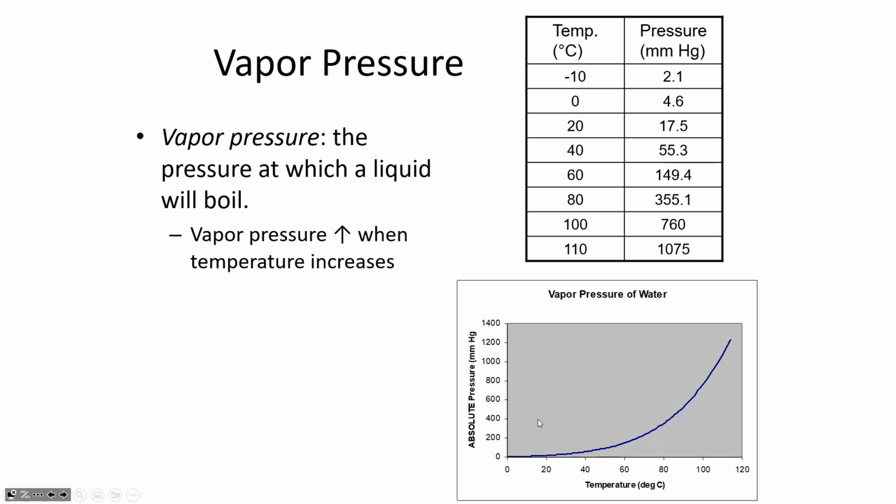Do you remember that lab that I'm talking about, where it had the little tubes coming up and you maybe traced with a pencil the shape of the piezometric pressure at different points? What do you remember about the pressure at the throat compared to the pressure before the pipe contracted? How did the pressure change when the velocity went up through that throat?